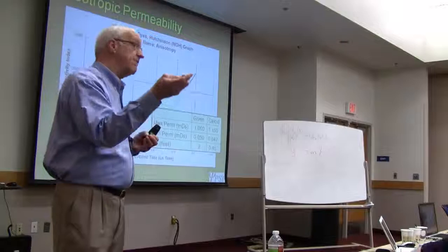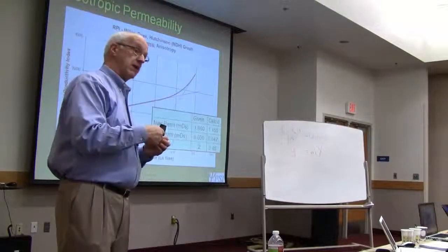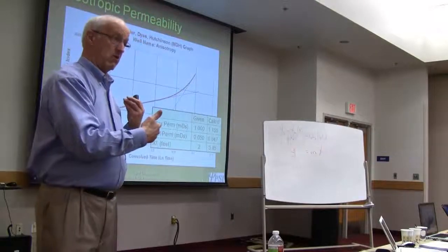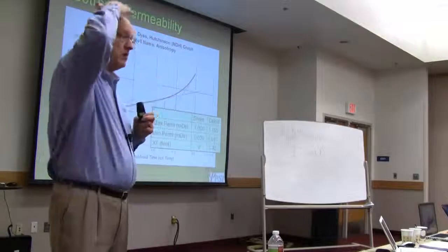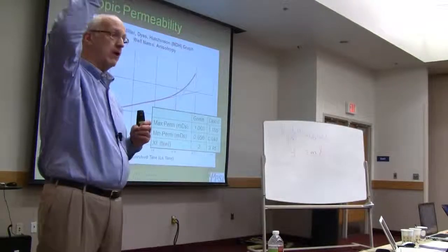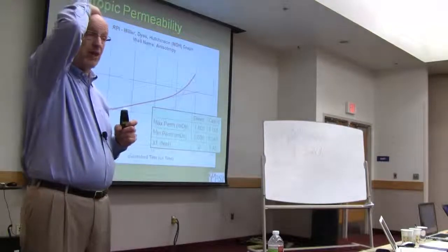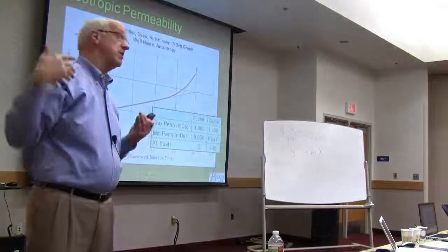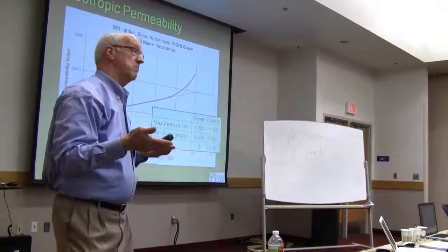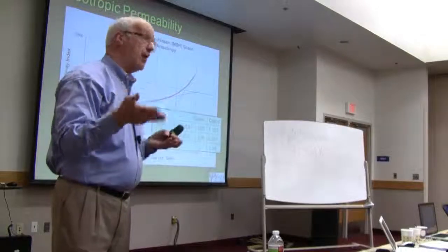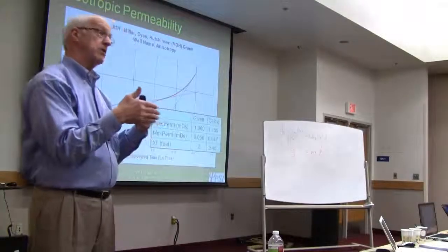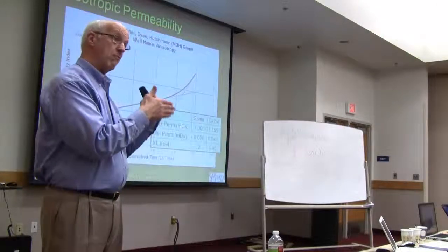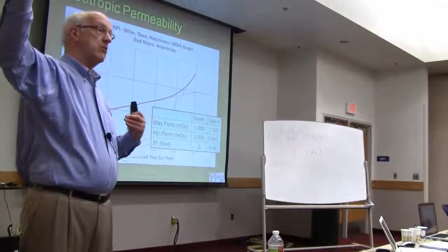Then comes the question of the effective length. Well, the effective length is that which is able to deliver fluid back to the wellbore. All right? And the sad news is when you start wrestling with the idea, I've got a whole lecture on that issue we won't have time to get to. But very likely, when you take into account the mobility ratio concept, you might be lucky to have the effective length be 1/10 of the propped length, simply because the mobility ratio is so adverse that if you pull the well too hard, you comb the gas and the oil in right at the wellbore, and the rest of that fracture is utterly useless.